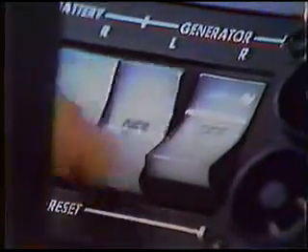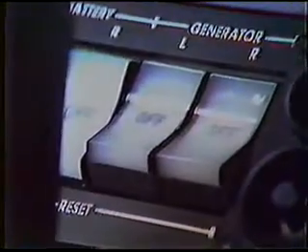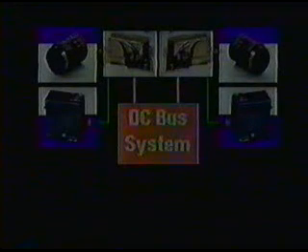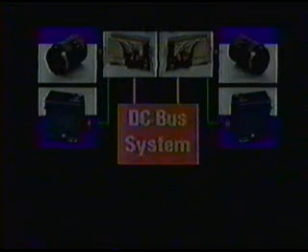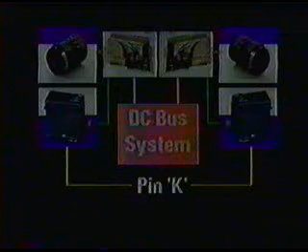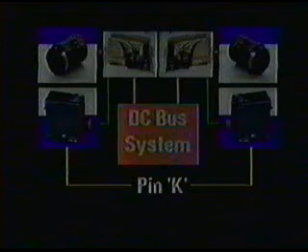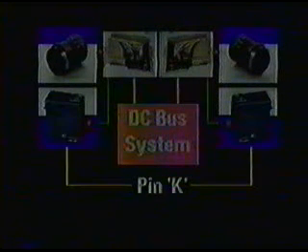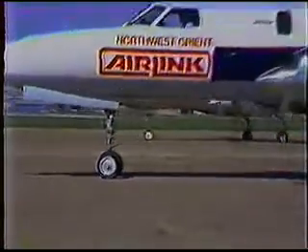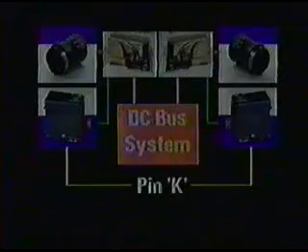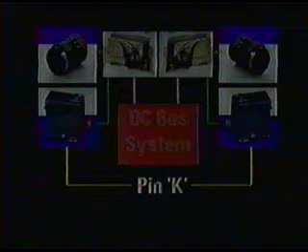The pilot now moves the second generator switch to the reset, then to the on position. Its generator control panel looks at the generator's output, and if correct, closes the respective generator relay and places the second generator on the line. The generator control panels now must look at each other's output to determine if the generator they control is carrying its proper amount of load. The pilot now operates other electrical devices in the aircraft. These devices increase the load applied to the bus.